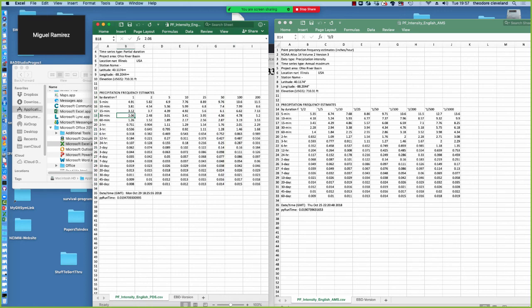And it depends on how recently the guidance manual's been rewritten. If the stuff is from the 80s and early 90s, it's likely that they didn't have access to partial duration series at the time. The theory existed then, but nobody had tabulated it. But if it's something from the late 2000s, they will probably have partial duration series, hopefully specified in the actual design guidelines.